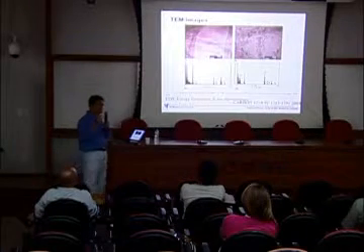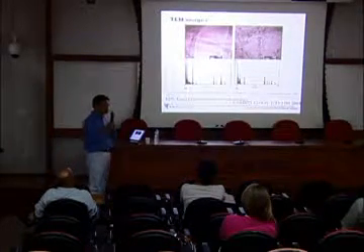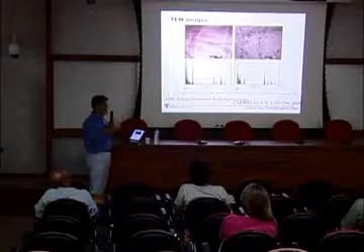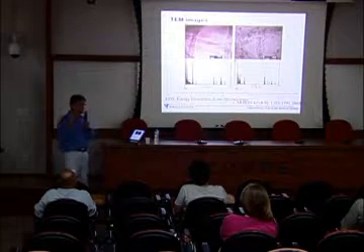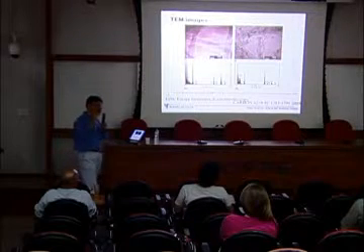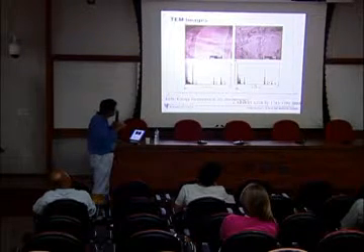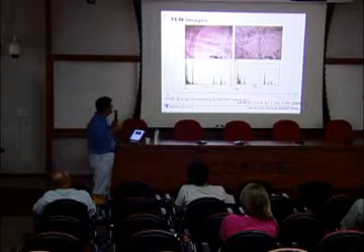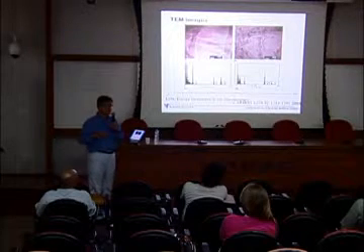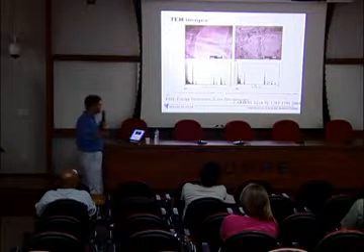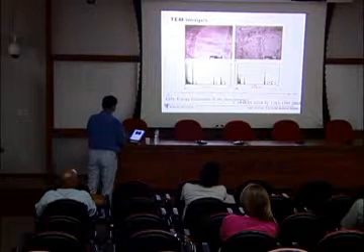So with a transmission electron microscope, we can see through the materials, but if the material is very thick, like 50 nanometers or 100 nanometers, then of course electrons cannot penetrate and we cannot see it. In this case, it's single wall carbon nanotubes, so you will see the tiny walls. The diameter of a single carbon nanotube is about 1 nanometer, and the wall thickness is 0.3 nanometer. So we can see through those bundles of nanomaterials. And in the right case, it's small particles. That's an iron catalyst to grow nanotubes.